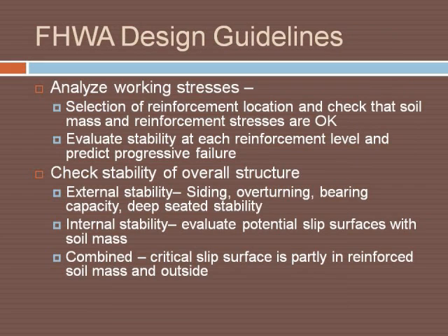Now that we know the different types of MSE walls, I'd like to briefly discuss the FHWA design guidelines. They want us to analyze the working stresses, check the stability of the overall structure, and perform deformation evaluations.